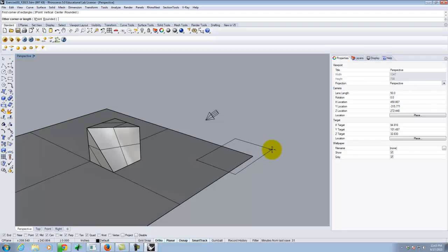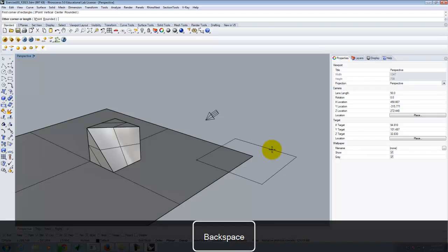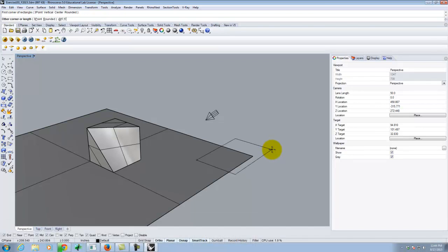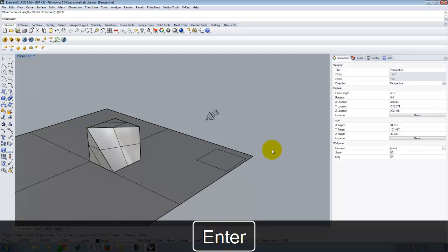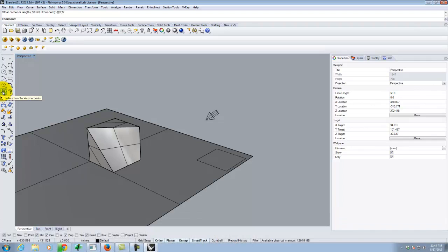And we'll do it over here somewhere. And I'm going to type the little at sign, 5 feet, comma 5 feet. We're going to talk through what these mean next class, because there's a coordinate system behind it, and we can use those measurements. But I'll go ahead and hit Enter, which gives me this shape. Then I'm going to draw a vertical plane. So I'm going to click and hold on the planes here and select vertical plane.